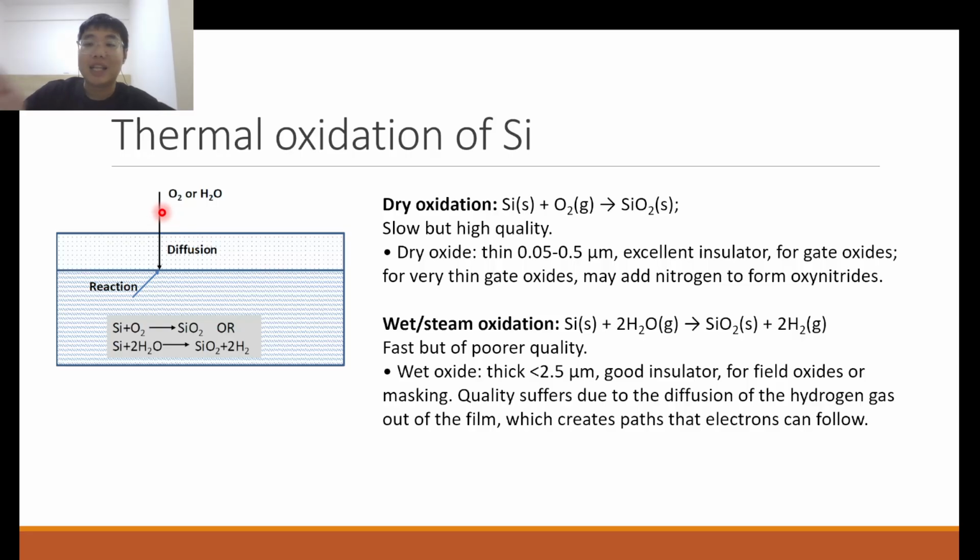So because it was added later, if a modified oxide with a different isotopic concentration is formed at the surface, then we know that silicon diffused through the oxide layer. However, we found that it is formed at the silicon and oxide interface, so we conclude that oxygen must have diffused through the silicon dioxide layer to react at the silicon and silicon dioxide interface.